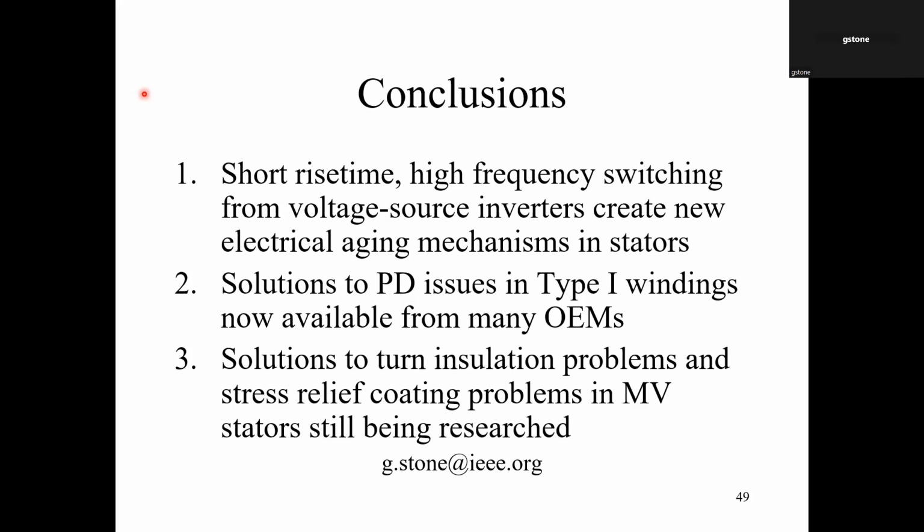You really need to be moving to a global vacuum pressure impregnation, where you pull a vacuum, put it in a tank, and introduce a resin that will cure. Maybe there are some accelerators in there, but by trial and error you get the right amount of time to allow the epoxy to penetrate and start to solidify. Then you push that resin in under pressure, so that you fill those voids. That's vacuum pressure, and then you apply heat to cure it.